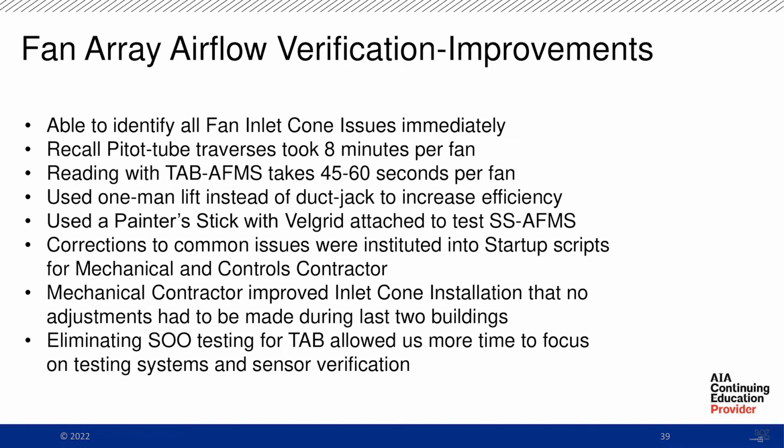We ended up using a one-man lift instead of a duct jack to increase efficiency. I talked about the painter stick earlier. The common issues we were finding, we instituted into startup scripts for the mechanical and controls contractors. These are some of the improvements we made during our fan array verification.